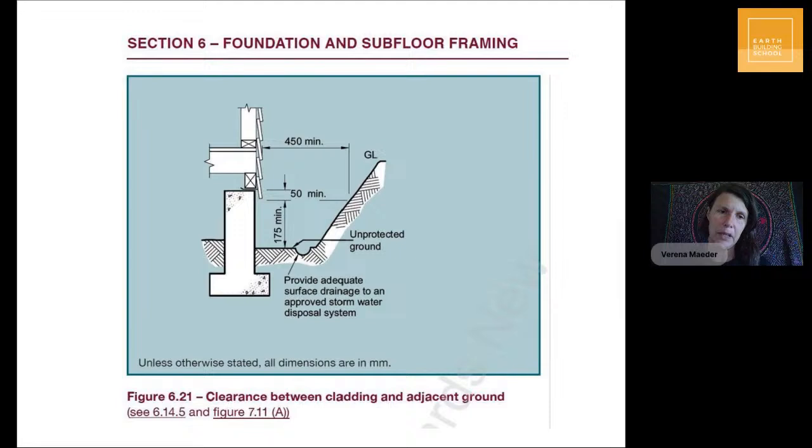So to have that flexibility, they don't anchor the whole building into the ground with a really big footing situation. They even build on skids. So just big timber bearers that are sitting on the ground that are tied down to the ground. It's also a possibility. The only thing is when you're dealing with any form of timber in ground contact, the timber has to be adequately treated. So just taking a note of that.